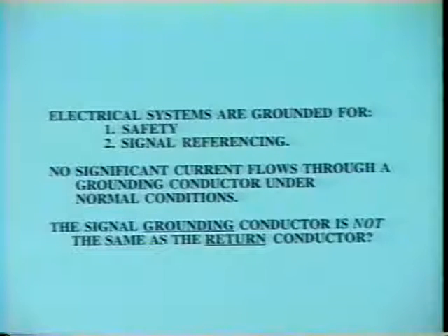In safety grounding, what we're trying to do is bond metal objects together that might become energized so as to reduce the shock hazard voltage that could otherwise exist between them. So safety grounding is bonding metal objects together to reduce a voltage difference. And the use of multiple grounding conductors is acceptable and even gives some little bit of redundancy.